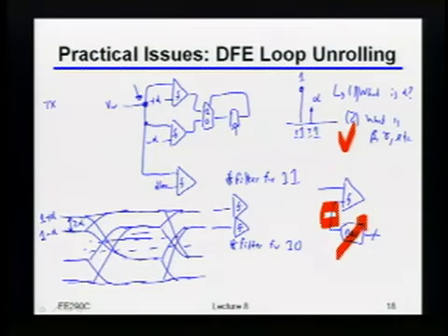So when you say you subtract and then divide by 2, you're doing that operation on the digital code? Exactly. I'm doing it on the digital codes, which does not mean that I'm actually doing it on the real analog levels at the output. Right? Because all I have to estimate here is the digital code values. So okay, actually, maybe you gave me a thought. Maybe there's some weird analog sample and hold thing you can do, but even that seems pretty tough. Okay, actually, maybe you can get that to work. But anyways, point being, if I really want this driven by a digital control loop, better build a good DAC.